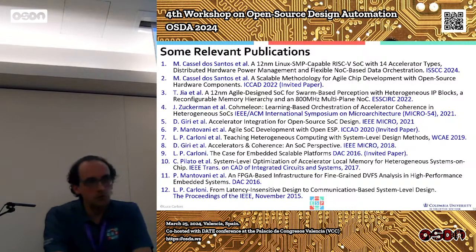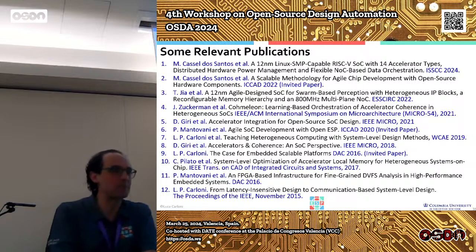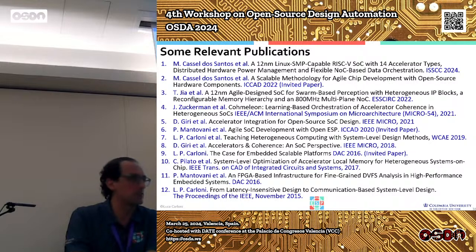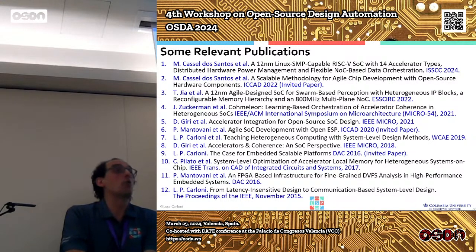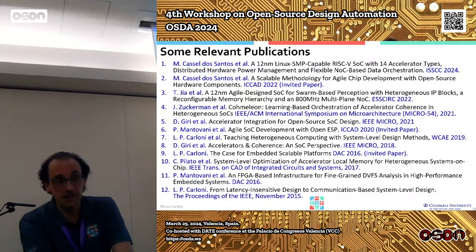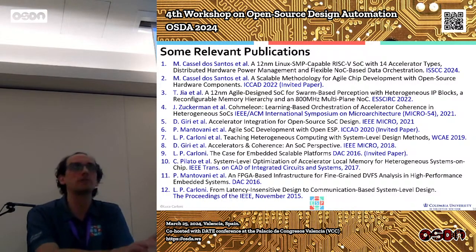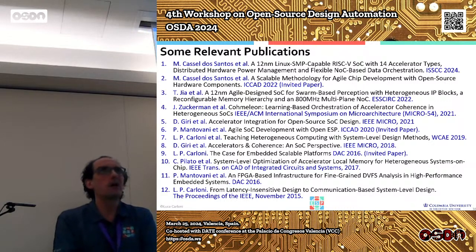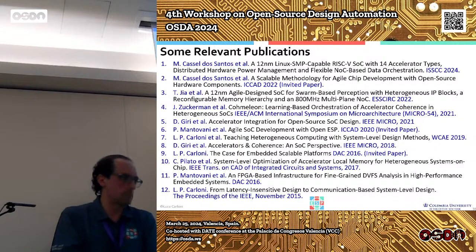With respect to the network on chip, as you know, I've done quite a bit of research on network on chip, and there has been an amazing community over the last 25 years doing research on a variety of networks on chip. In the end, for ESP, we made a very important decision, which is that we use something relatively simple: a 2D mesh, no virtual channels, but multiple planes. So this is why, for instance, for cache coherence, to guarantee absence of protocol deadlock, we have to use 3 planes, because we don't have virtual channels. And then also in terms of protocol and flow control, fairly simple stuff.